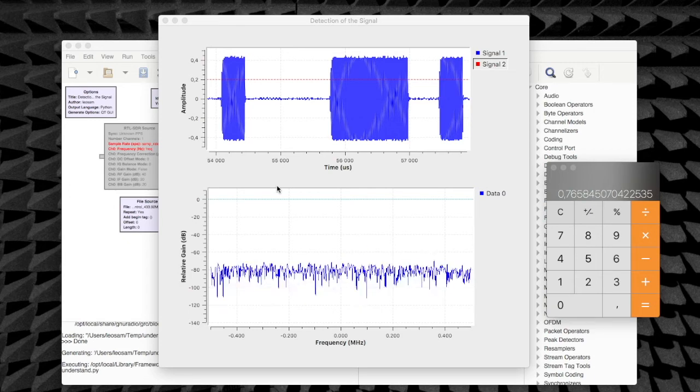Why do I guess that? Because I'm used to seeing these kinds of things, and I know that this is a very convenient way to encode information, such that if you have any problems with the amplitude of the signal, you can still look at the timing of the signal and decide if this is a 0 or a 1.